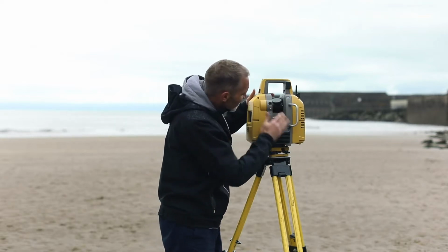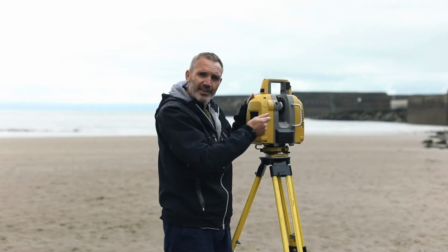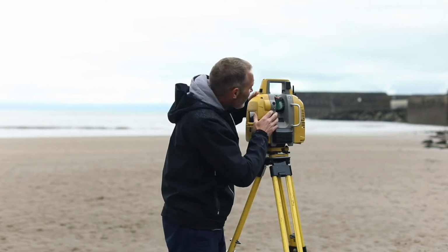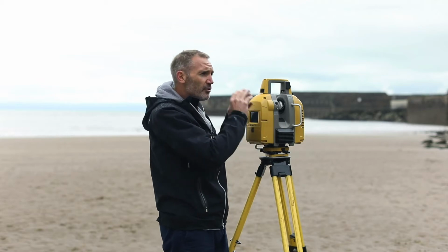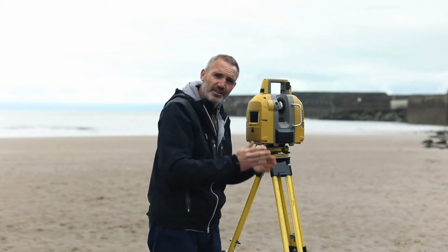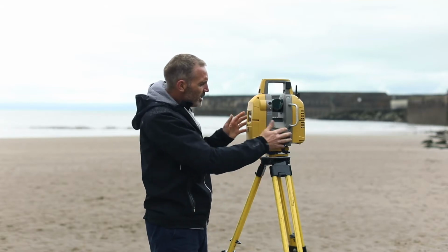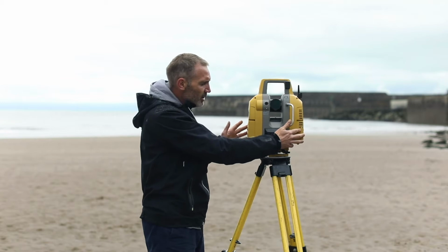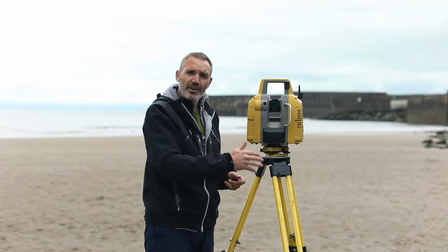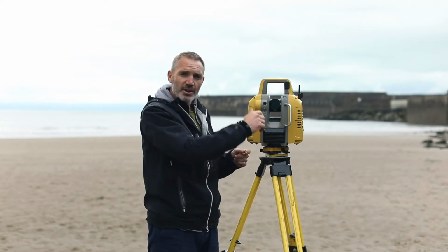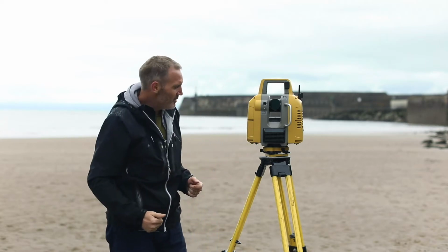So how does it actually get the distance? Well, it knows the horizontal angle, and it knows the distance, just like the distos that we use in DIY, and then it also knows the vertical angle. So using those three components, it's able to solve the three-dimensional coordinate, which I just explained, of any distant point. So just to recap on that, the instrument rotates slowly through 180 degrees. It's transmitting up to 1 million points every second, and it's measuring a three-dimensional coordinate through a whole dome of data within the range of the instrument.